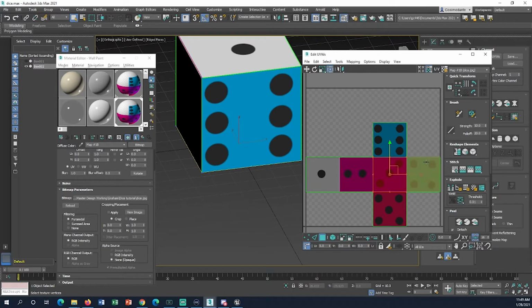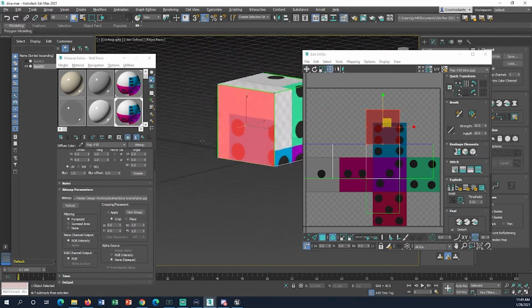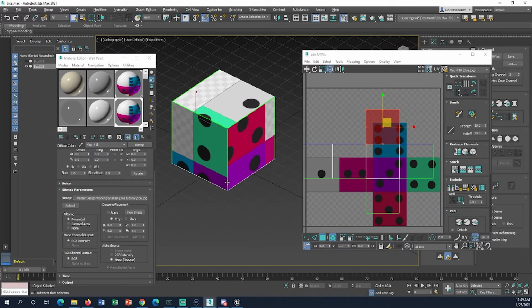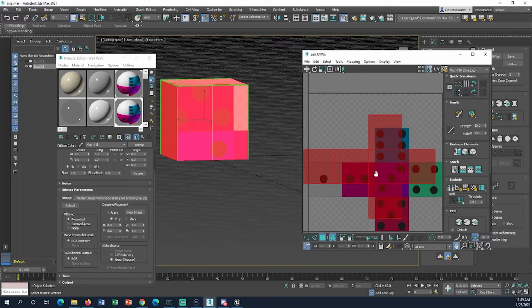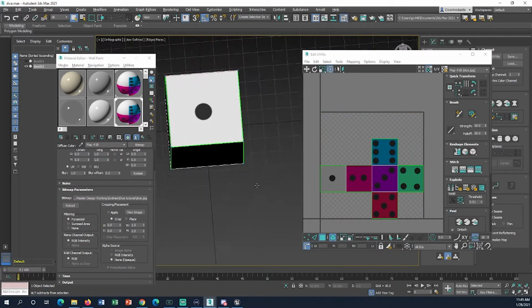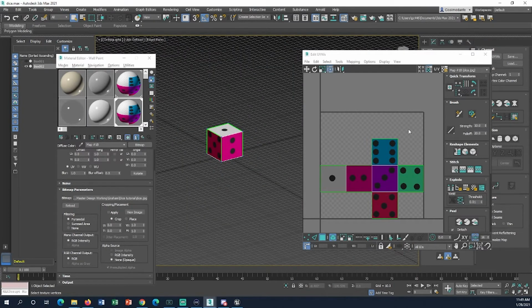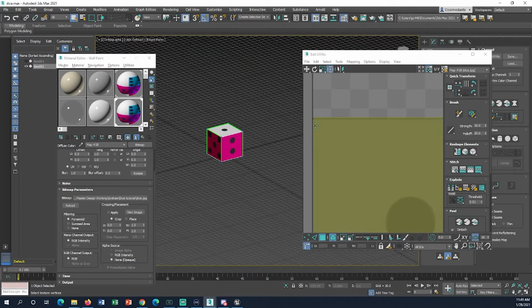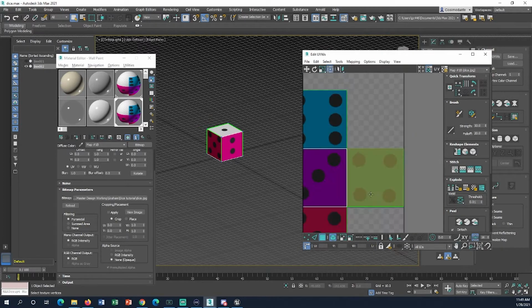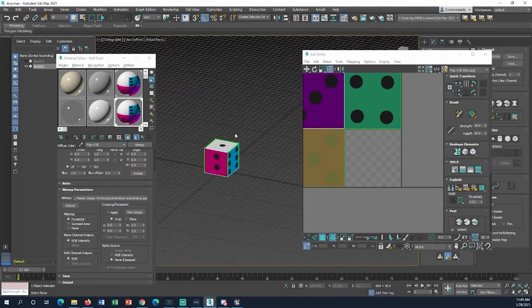So let's just go over here, select it all, and move it. When I move it, you can start to see how it can easily get messed up and you can start getting these weird factors. So for you, if you unwrap it and it's like up here, you just have to drag it down and align it up nicely. And there we go. Alrighty. So now that we have it unwrapped, all this stuff all nice, make sure we have our little gaps over here. Don't want anything to be leaking out because that will be messing up our light maps.